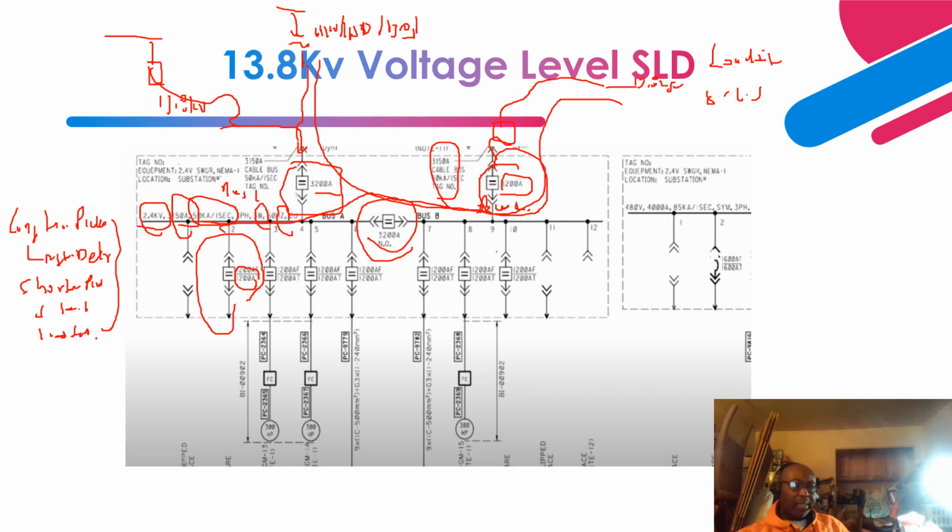So as you can see over here, this is basically an equipped space, right? And this is a spare. That is, it has a cubicle that has a breaker already dedicated that can be utilized in the future. All these are part of the design stage. You need to think about the future and plan for it.